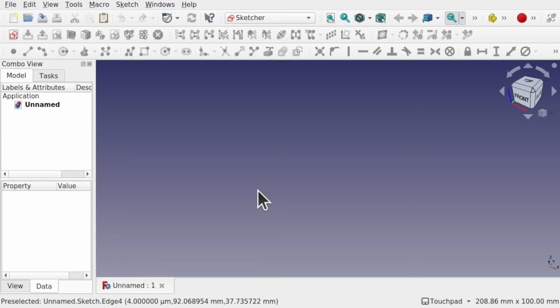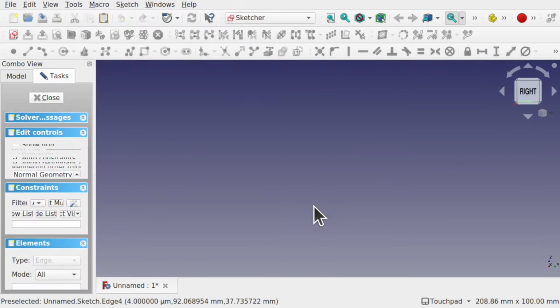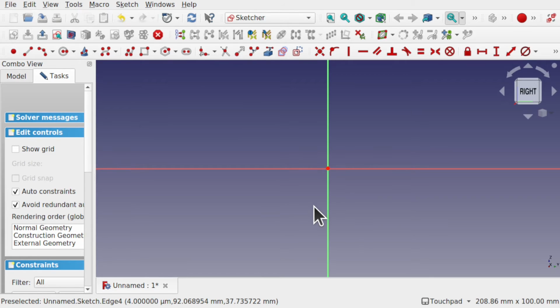So for safety, we will create a closed sketch to create a solid profile. I'm in the sketcher, I'm going to create a sketch. I'm going to go along the YZ plane because we're using the profile along the side of the spoon. Now remember, back to the spoon, we're looking at 3 profiles. The left and right one are going to be the same, the middle one's going to have the curvature on.